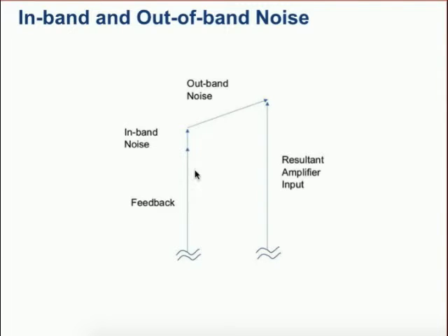If we're only just outside the oscillator bandwidth, then the feedback vector will follow to some extent the movement of this out-of-band noise. If we go out close to the noise floor, then the feedback vector will have virtually no dependence on the outer band noise. And bear in mind, this is normally represented on a logarithmic scale, and there's a vast difference in influence that this outer band noise has on the feedback vector across that range.